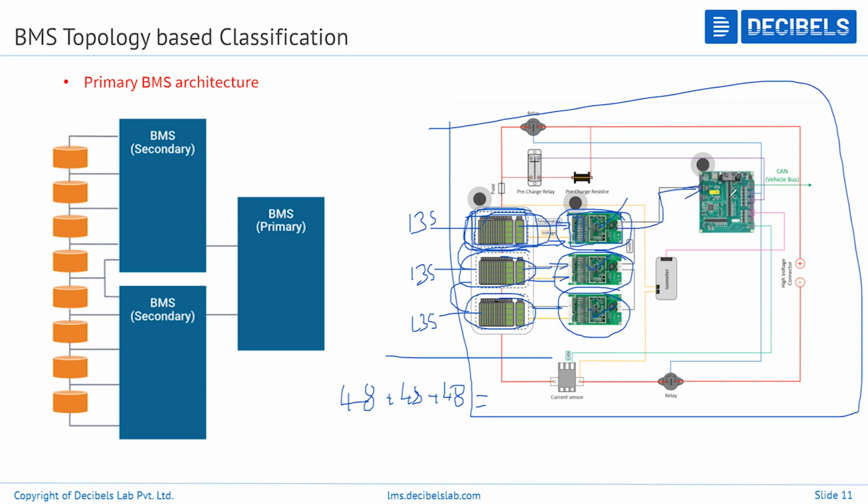So let's say you want to cut off the battery when there is an over voltage or under voltage, or if you are trying to draw more current, or if the temperature is high. Okay, then you want to make the decision whether to supply the current or not, or whether to charge or discharge. So that logic will sit in the microcontroller. Okay, and even the SOC estimation, SOH, sorry, SOE. All these estimation algorithms will sit over here.